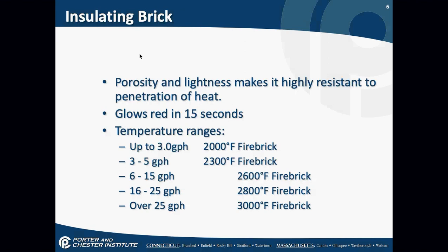Okay? There's different ratings of fire brick that can be used. Up to 3 gallons per hour, you might use a 2,000 degree fire brick. 3 to 5 gallons an hour, you use a 2,300. 6 to 15 and you go up. Over 25 gallons per hour, we use a 3,000 degree fire brick. Now, when you start dealing with 25 gallons per hour of oil, you're dealing with a lot of flame. A lot of requirements in that range.